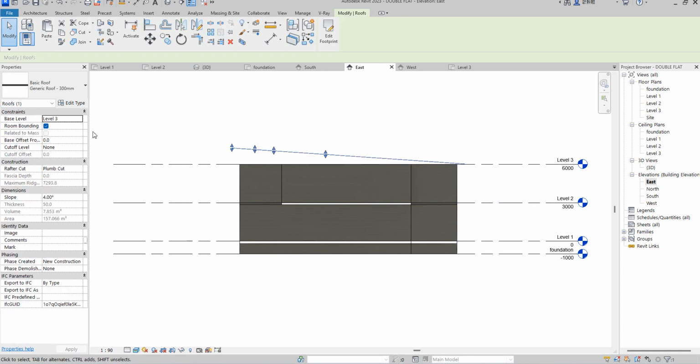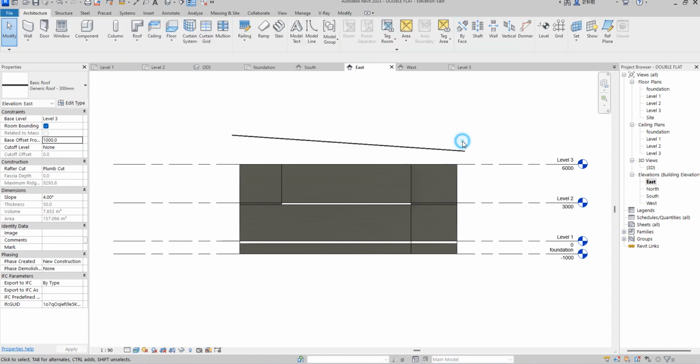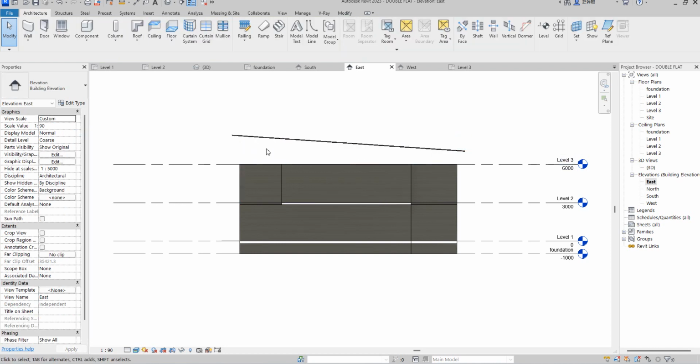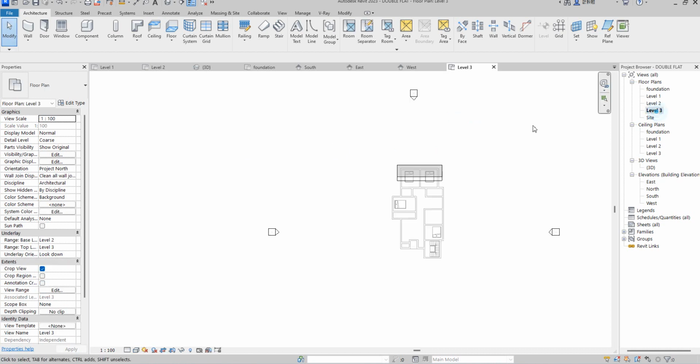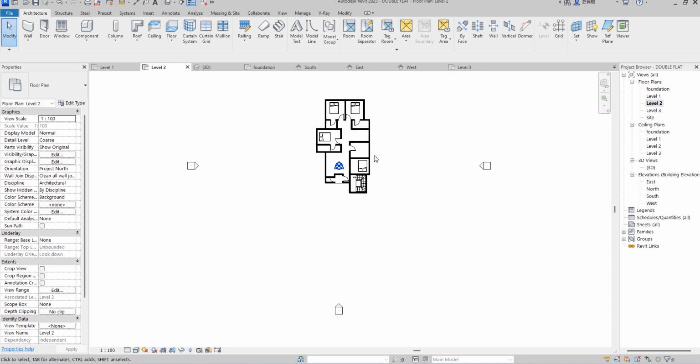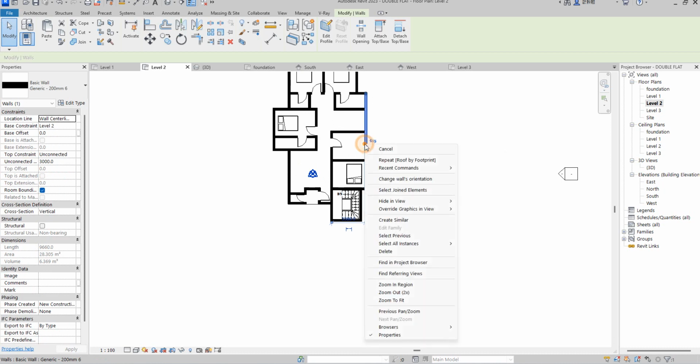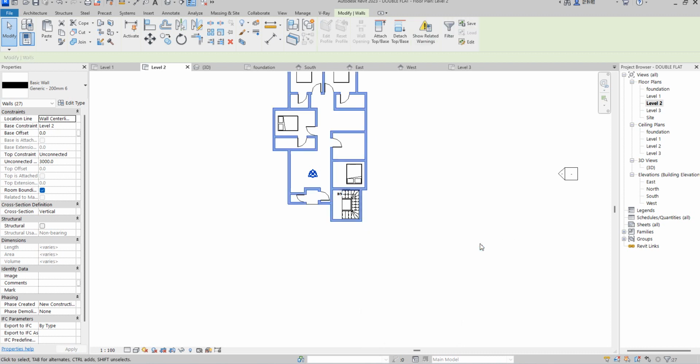So I'm going to raise this particular roof. We raise it up here. So offset for me 1000. This 1000 is going to be of a different gauge of relevance for me again. So what am I going to do at this level? I'm going to select to the level 3. At the level 3, I want to select, no, let me go to level 2 because that's where I have the whole thing. So select all instances in this level. Select all instances in this view.